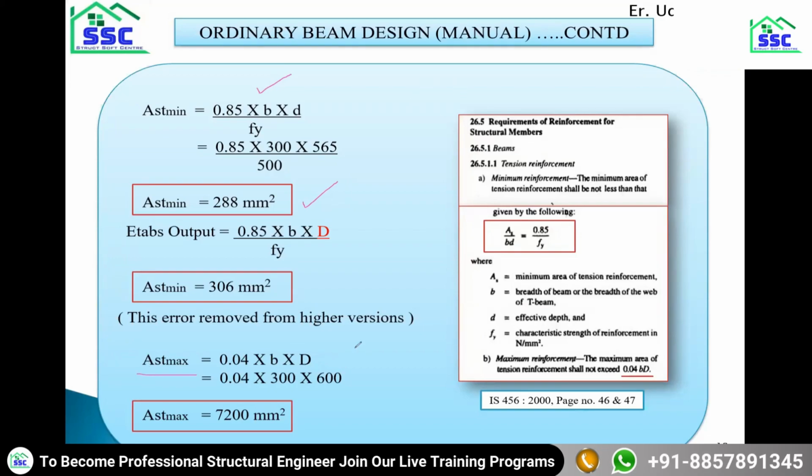Now let us go to the next part, which is AST maximum. This is also given to us by IS 456-2000, page numbers 46 and 47. The maximum tension reinforcement that we can put in the beam has a value of 0.04 BD, which is nothing but 4%.